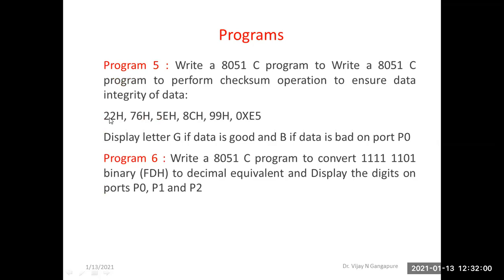In the end you will receive this checksum byte at the other end, and you can check the integrity of the data received. How? You have to just add all these bytes. The first 5 are data bytes, and the last byte is the checksum byte. So if you add all these bytes together, ignoring carries,